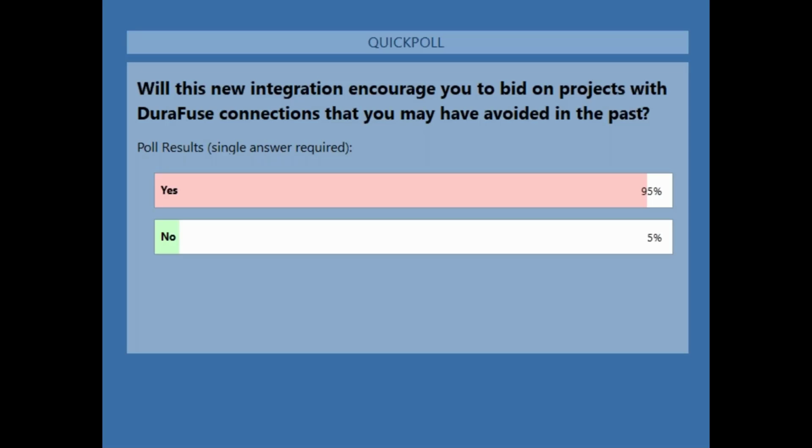What is the purpose of those long slots in the fuse plate? Yeah, so I don't know that there are long slots on the fuse plate themselves. The bolt holes in the fuse plate are oversized holes, and that's to accommodate fit up and erection. On the top plates, there are oversized holes and long slotted holes, and those are to accommodate fit up and erection to make it easy to put the connection together on site.